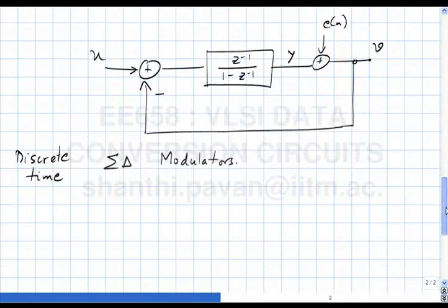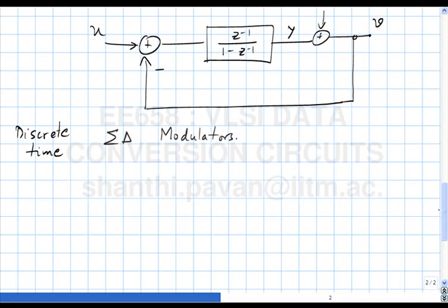All right. So then people start asking the question, well, if this has to be a sampled signal, correct? Before you do sampling, what is the operation you must do before sampling? Anti-alias, correct? So the question people start asking is, hey, if I need to sample here, if I had a continuous time input, u of t, I must put an anti-alias filter, and then sample. See, oversampling greatly reduces the kind of anti-alias filtering required, but you do still need an anti-alias filter,